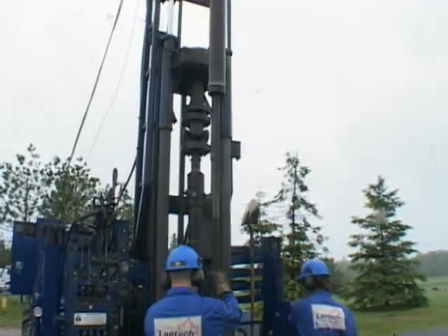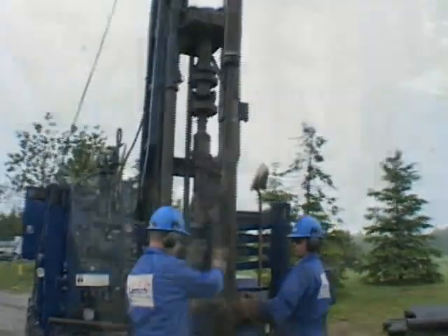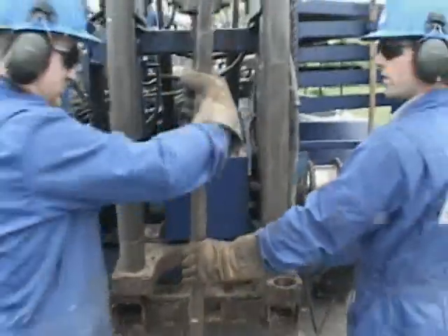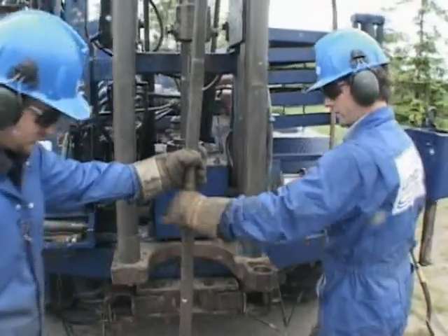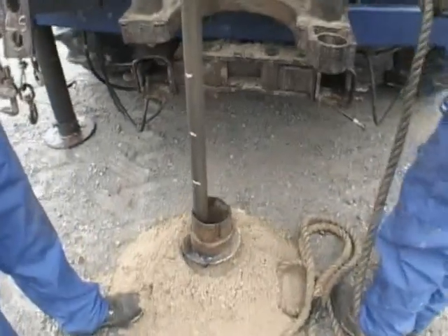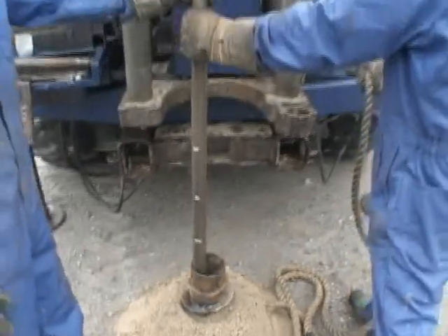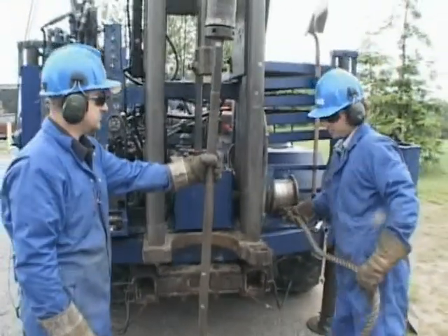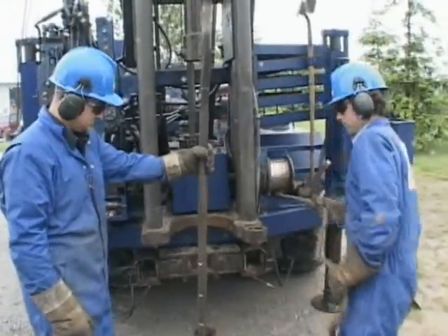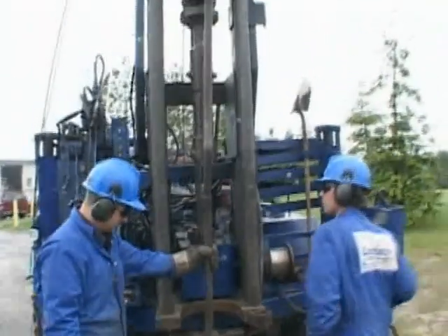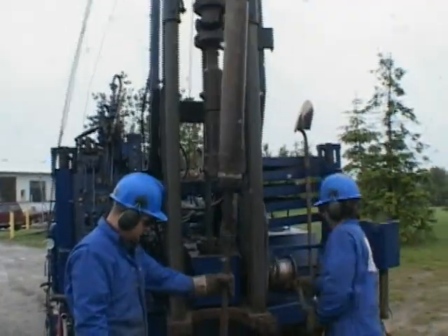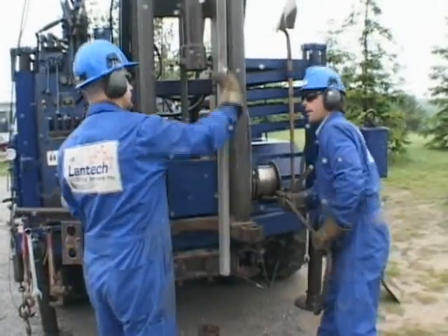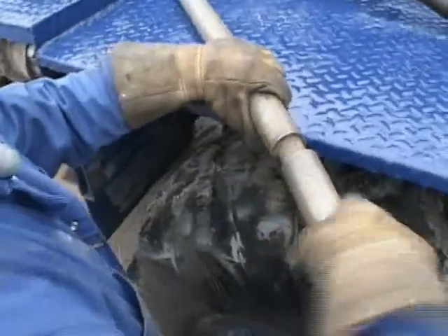The standard penetration test uses either an automatic hammer or the cat head to lift a 140-pound hammer, which has exact travel of 30 inches. The number of blows required for penetration are recorded. The split spoon device then reveals a representative sample of the geology.